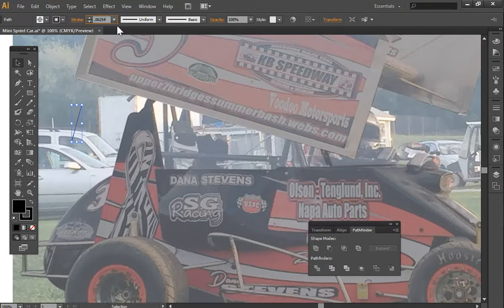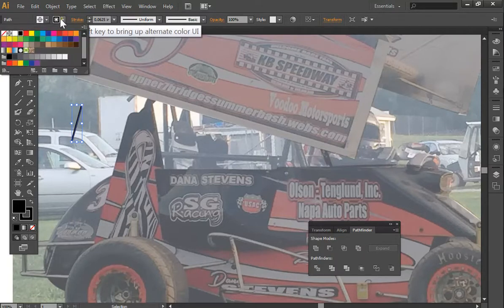0.0625, and the reason I use 0.0625 is, a lot of your plasma cutting systems, fine tip consumables, produce a cut width that's 0.03 to 0.04, and so I usually go 1.5 times that width when I'm doing a single line cut path. When I do that, it allows for a little bit of additional offsetting between your cut paths, and it's just something that I've developed over time.